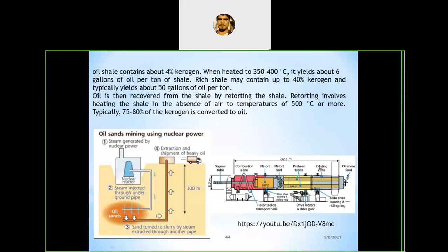What happens in the conditioning drum? While combining all these substances together, a slurry is formed. Then the slurry is passed into a separation tank, where the coarse sand settles at the bottom. In the tank, the coarse particles of the sand settle at the bottom, and a froth of bitumen, the bitumen and the water with fine material matter, forms on the top.